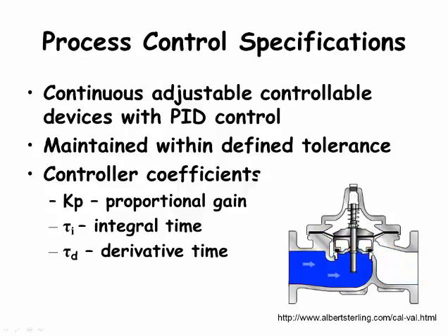One aspect of good control is staying within user-defined tolerance limits. For example, a person using the fluid heater we've been studying could specify that she wants the fluid temperature to be 41.5 degrees Celsius plus or minus 0.3 degrees Celsius. With this type of process performance specification, the outlet temperature can be monitored to see what percentage of the time the outlet temperature is within the specified tolerance and what hopefully small amount of time the outlet temperature is outside the specified tolerance limits.